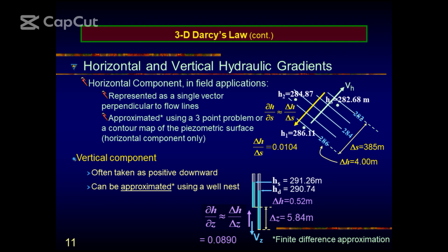By the way, what is the relationship between piezometric head, pressure, piezometric head, phreatic surface, and water table? Water table is for unconfined aquifer, the level of water. The piezometric surface is for the confined water level. It's for the confined aquifer.